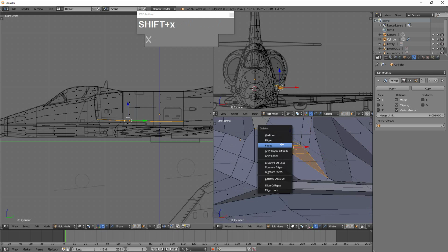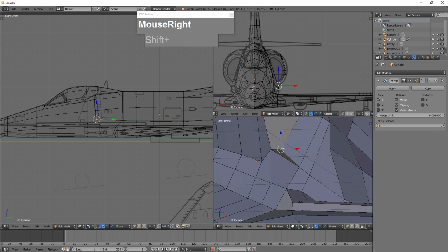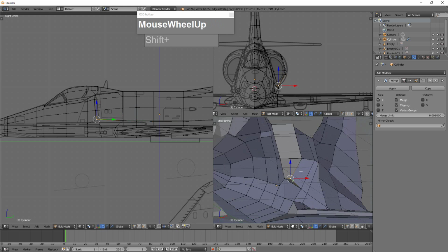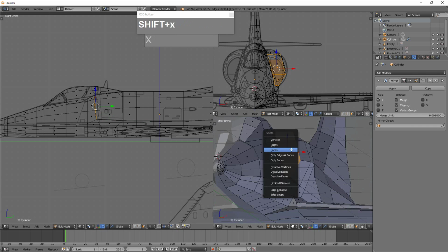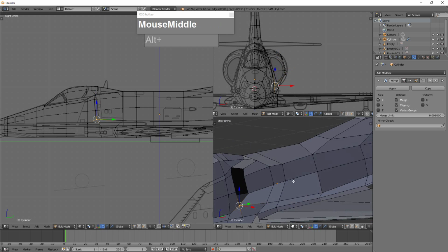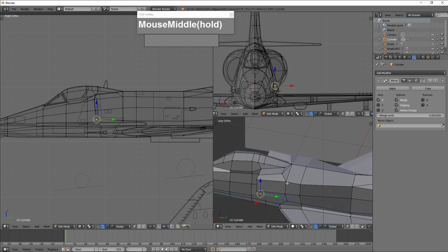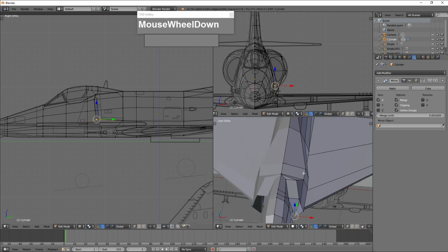So select this outer one, inner one, Alt M, the last vertex to snap in, Alt M, the last vertex, and then select this one. And okay, for this one I can select these faces and then press X to delete away the faces because I want to fix this. Alt M and join the last. So I've created my jet intake. It's a bit messy here because I forgot to remove my clipping, so I ended up with a triangular face here instead.